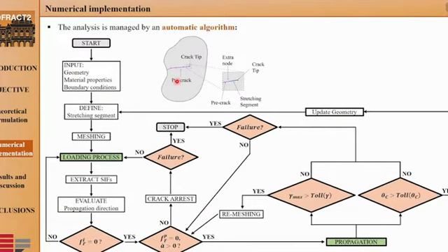After this, the code creates the mesh and starts the simulation, which involves a loading process. During each step, the dynamic SIFs are extracted and used to assess crack initiation condition. When this condition is fulfilled, the dynamic propagation takes place. The tip velocity is evaluated through a classical fracture criterion.